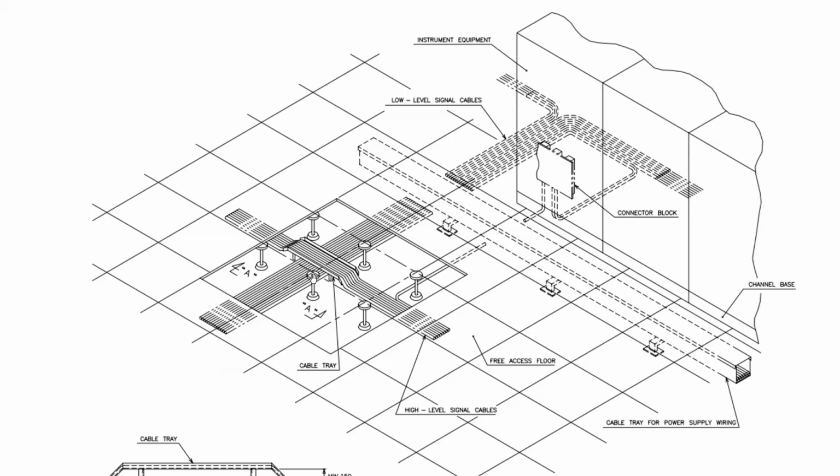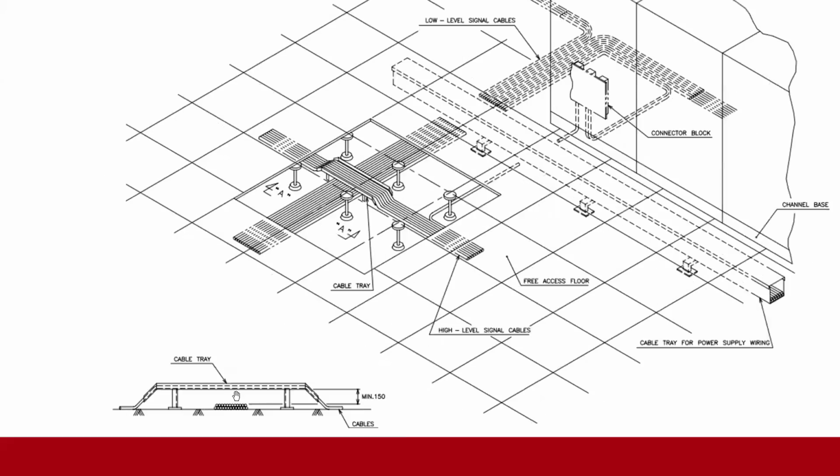When there is a crossing, see how there is a bump, right? There is a bump with around 150 mm spacing. Accordingly, the tray and support are provided. And you see here the section AA, I just cut this. This is the cross sectional view of AA. See, this is your low level signal cable. Then the tray is there with the support, and on top of that we have this high level cable with a minimum space of 150. Okay, this is one example.